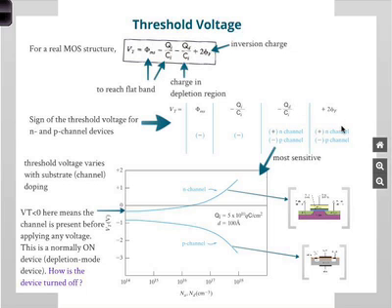And the same thing for the Fermi, the strong inversion condition. For an n channel, you're bringing it down. For a p channel, the opposite thing happens. You bring it up. Make it from n-type to p-type. In the case of the p channel, you're accumulating. Under inversion, you get holes at the interface. So keep that picture in mind.